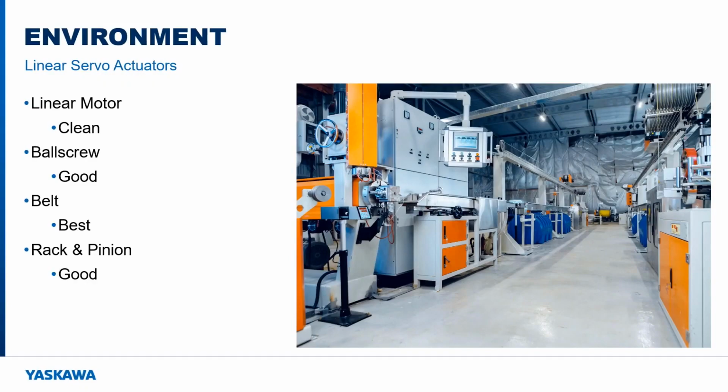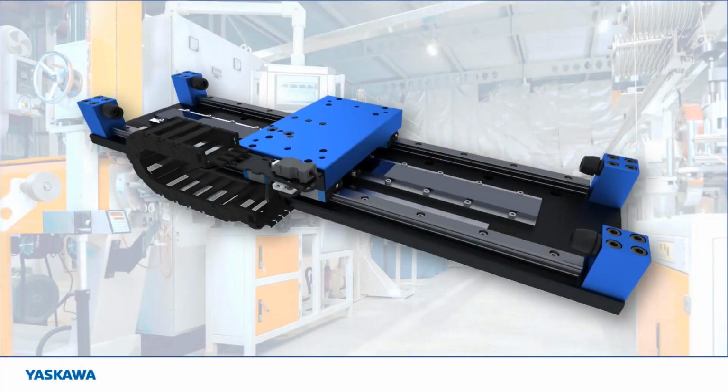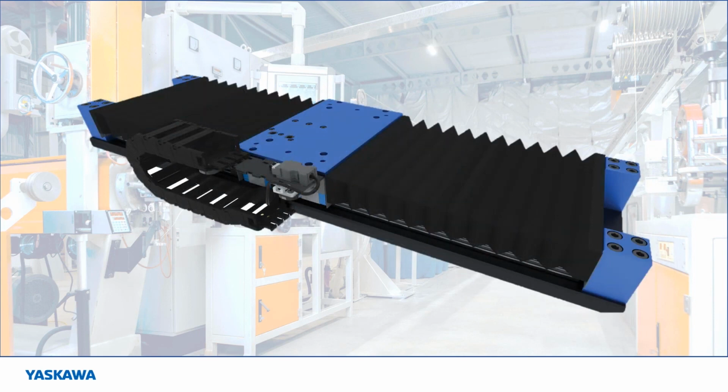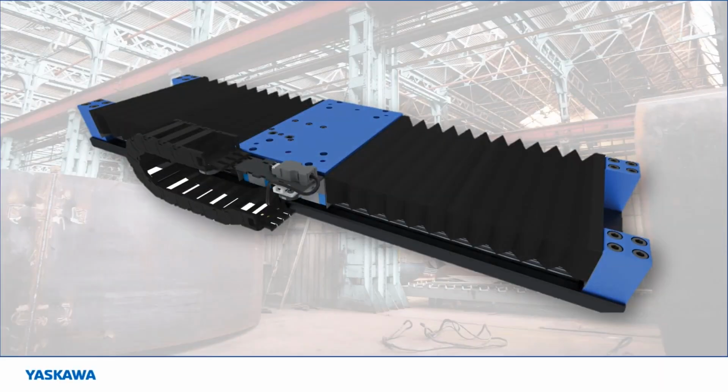Different mechanisms are best suited for different industrial environments. Consider the magnetic field of the magnet track of a linear motor, which may attract particles. A bellows protection system will help keep particles out of the magnet track. While linear encoders don't require a clean room, they do their best in a reasonably clean environment free of excessive dust and oil. The linear scale can still work with some interference, but for very dirty environments, consider a custom linear motor with an inductive or magnetic linear encoder.